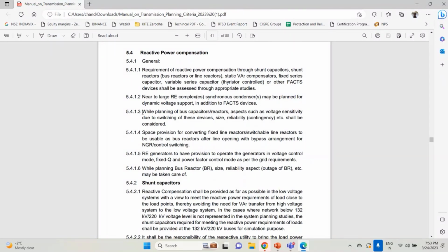The generator was generating, and that generator's active power you are converting into DC power, and then it is feeding back directly to the motor itself, right? And through that control you are changing the reactive power of the generator by increasing or decreasing its field current, right? So here the field current input you will take from the system itself.